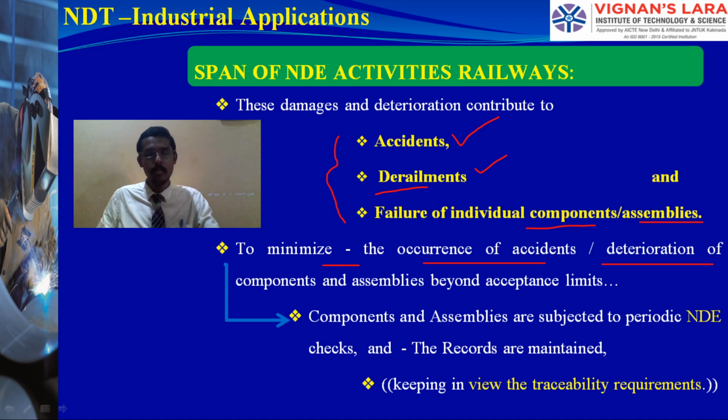Frequently we have to go for inspections at the in-service location, and we have to check the tracks every half a kilometer, however, 1 kilometer we have to inspect the tracks. In such a way we are able to do visual inspections, or maybe eddy currents, or radiography, or magnetic particle surface or subsurface inspections. Mainly ultrasonic will be helpful because all the railway tracks are connected, so we can keep on moving the component. Ultrasonic is the most important, useful technique in the railways.